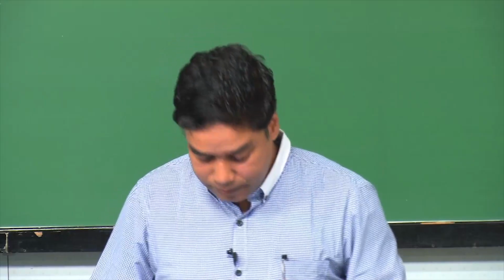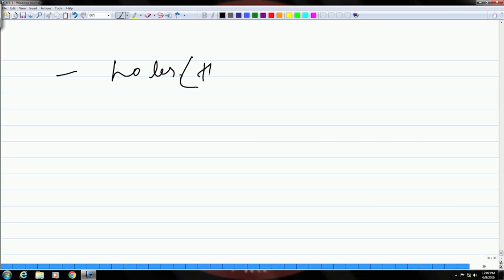If you have hollow parts, what kind of particles you can apply? You can apply a slurry or magnetic paint kind of thing or a magnetic rubber. Okay. So, like holes in thread holes.